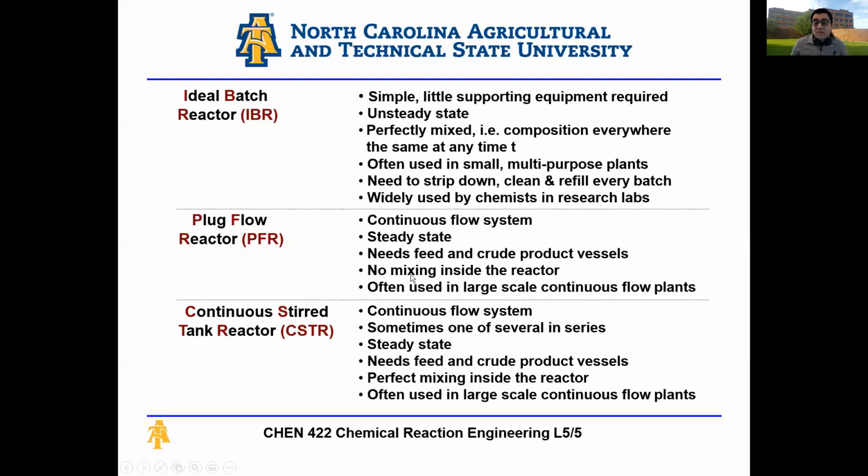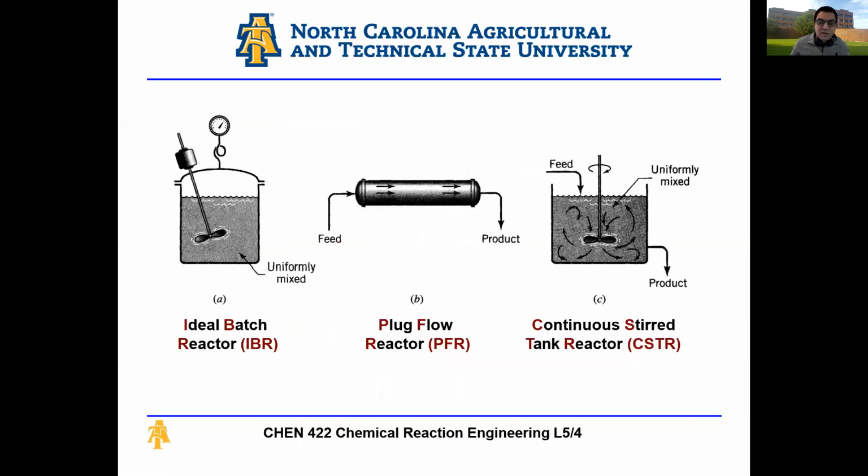There is no mixing inside the reactor. So the idea of a plug flow, let's go back to the previous slide. The whole idea of a plug flow is that we assume that the flow inside this cylinder, for example, consists of elements, and all the elements are just pushing each other, right? There is no mixing between the elements, so there is no mixing along the flow direction.